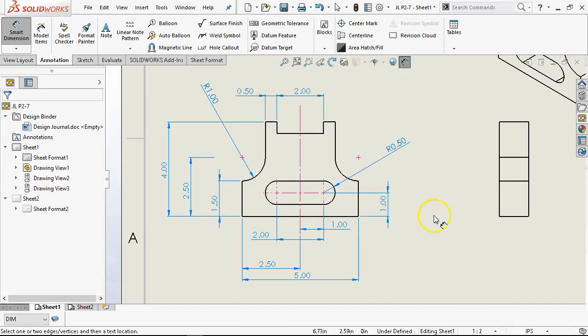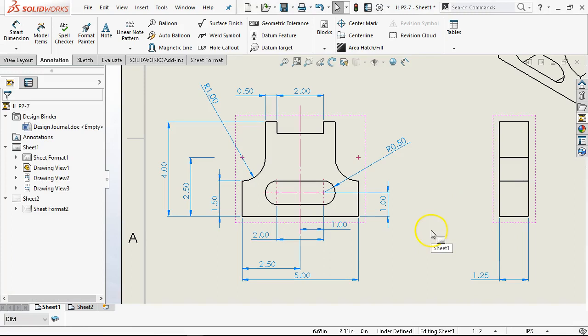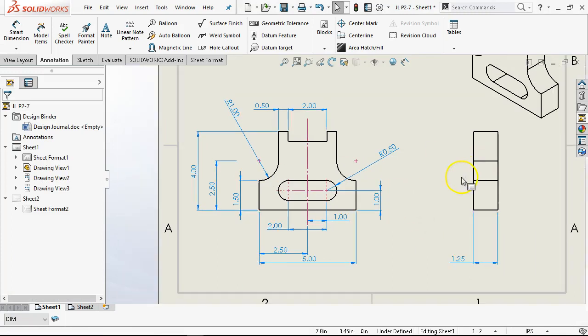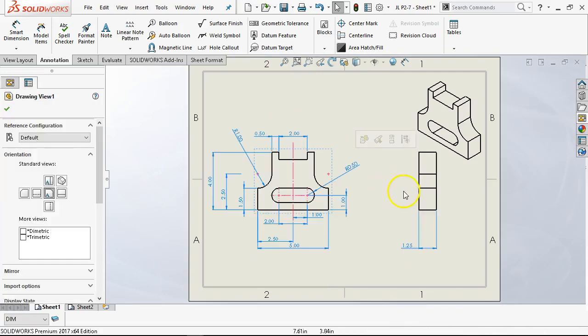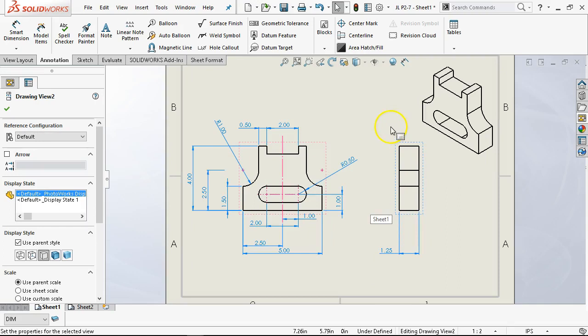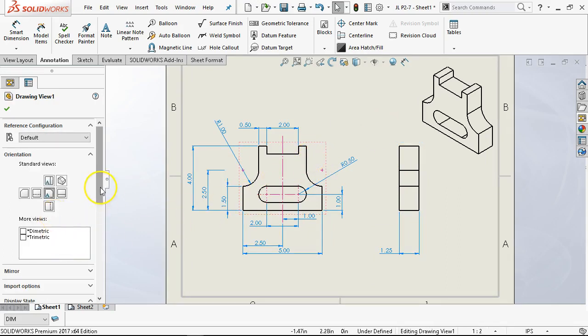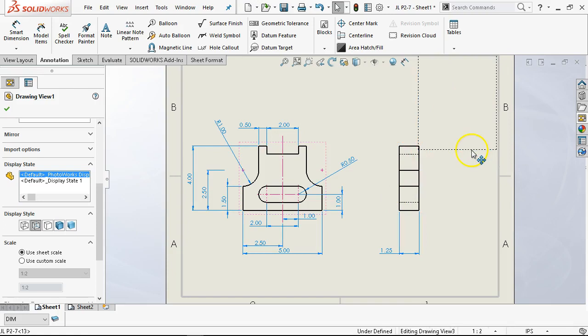All right, so other than the thickness, there isn't really anything that I needed on the right view. I could maybe put the overall if that helped out, and there wasn't really anything on the top view that would have gone through. So again, my preference is the hidden lines removed, unless it adds something, because we're going to get two lines in the isometric.